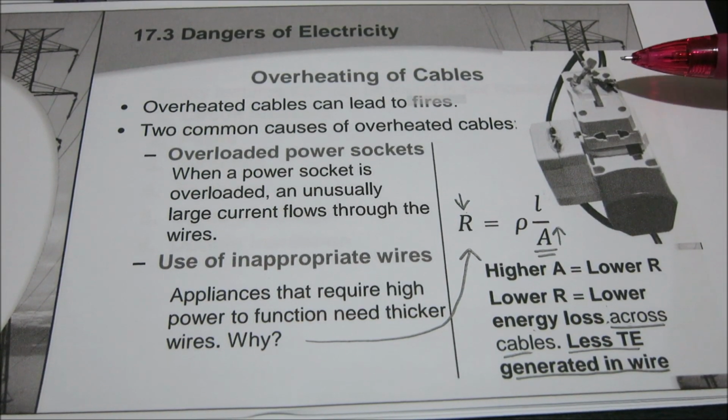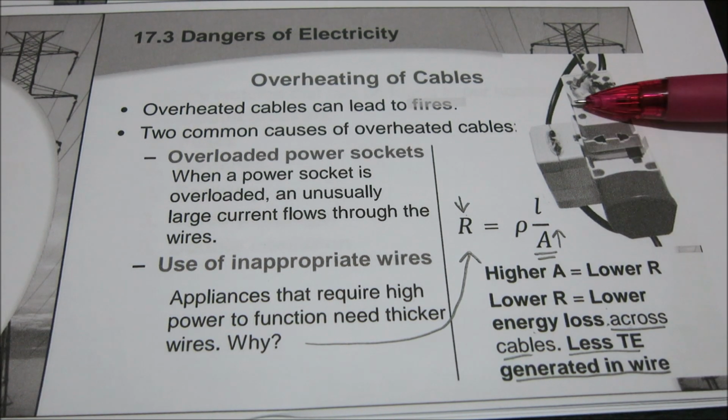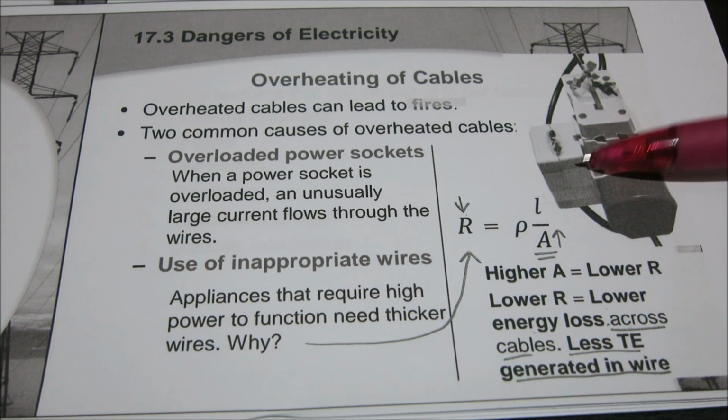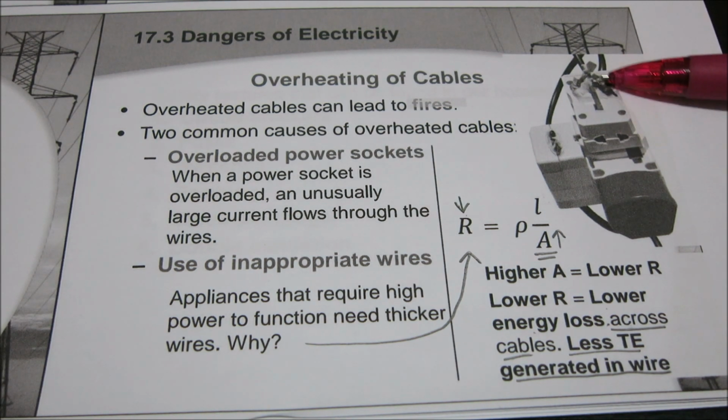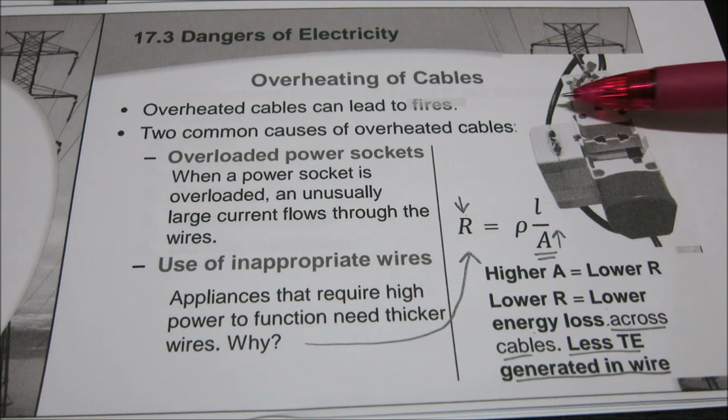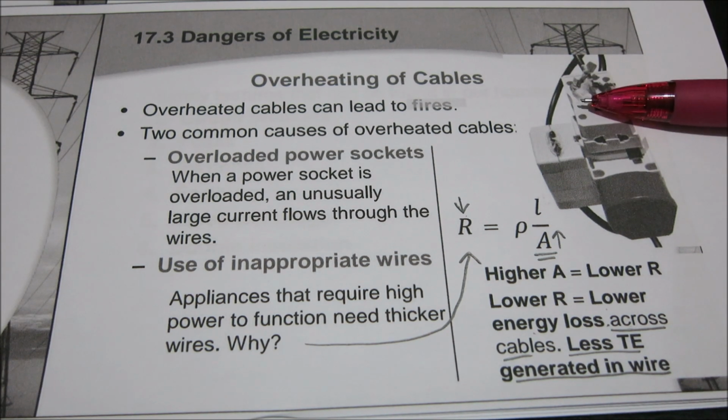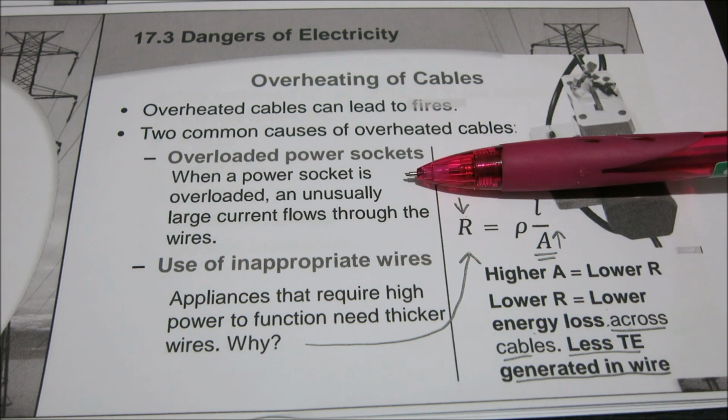So what is happening when you put too many into just one socket is that you're overloading the socket. It means you are drawing too much current from this just one socket. That means the cable that is supplying this may overheat. And when it overheats, then if you have any flammable materials around, then that will catch fire.